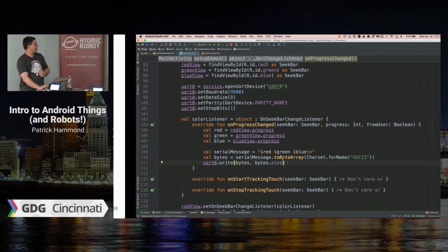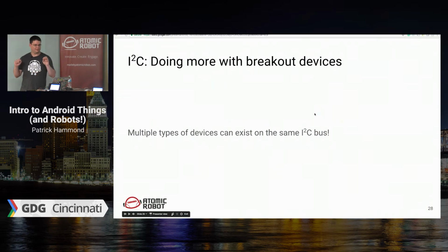When you're doing things with these other devices, like the thing that's controlling the servo, and the thing that's reading the values of these sensors, you typically have some type of driver interface that lives around these that knows how to interpret all the bits to send back and forth. To do that, you end up looking at the fact sheet for these things, which are 50-page plus documents that will put you to sleep faster than any book I've ever read. And they're like, okay, make sure to put this bit here, and this bit here, and invert this one depending on the state. If you're going to go through that process,